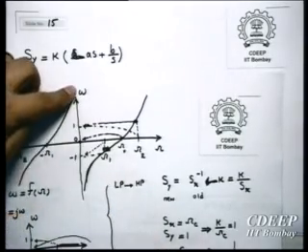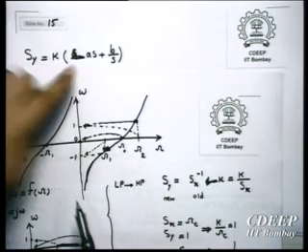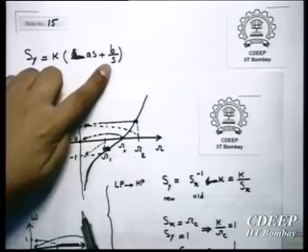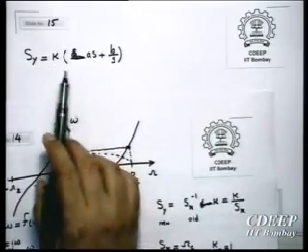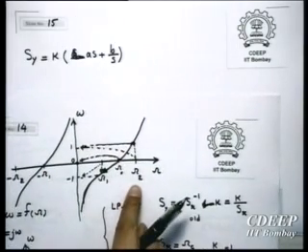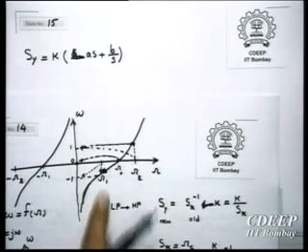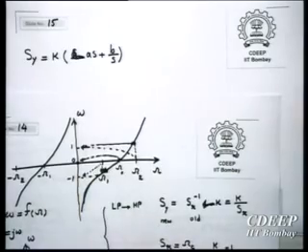So this small omega is for the low pass filter and capital omega is for the filter I would like to have. Therefore, this should be transferred to infinite. That is the reason I put S and 1 upon S. Now, how many variables do we have? Effectively, we have 2. Therefore, we can consider omega 1 and omega 2 and then see what the value of omega 0 will be, which will generate 0.